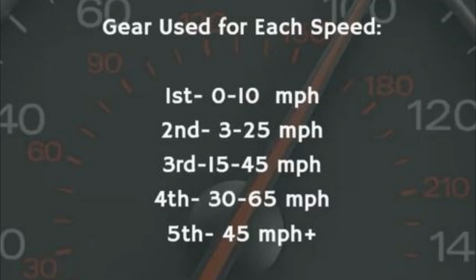In modern manual transmissions, various design improvements have been introduced to enhance safety and smooth operation of reverse gear. Some vehicles are equipped with synchronized reverse gears, while others use mechanical or electronic interlock systems to prevent accidental engagement when the vehicle is moving forward. These systems reduce gear damage and improve driver safety. Additionally, the clutch must be fully disengaged before selecting reverse gear to avoid gear clash and ensure smooth engagement.